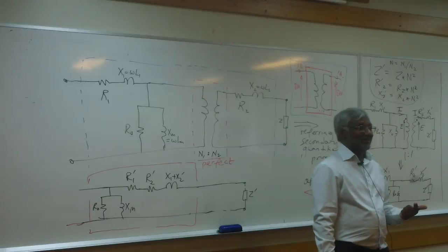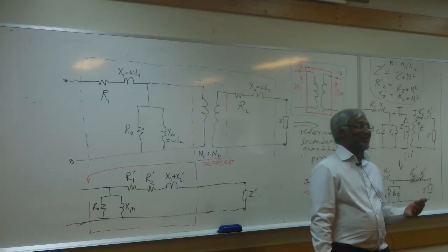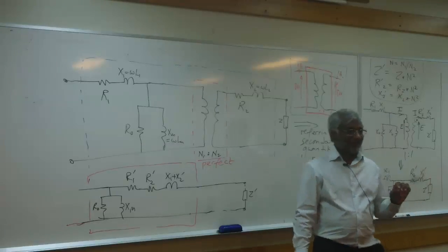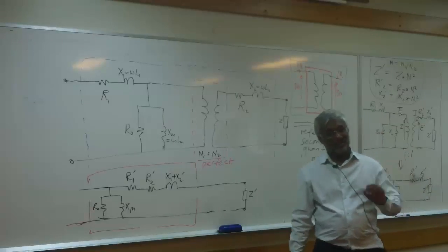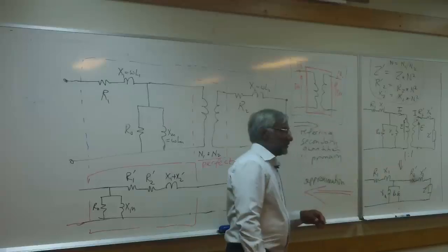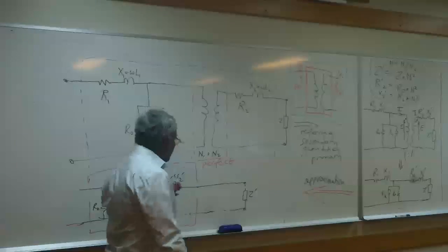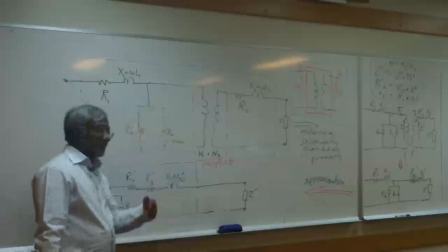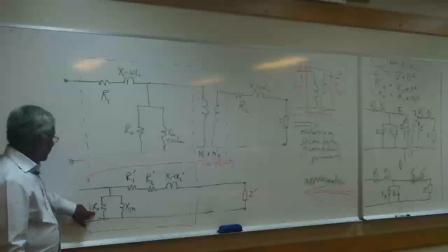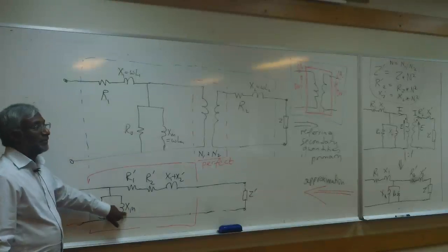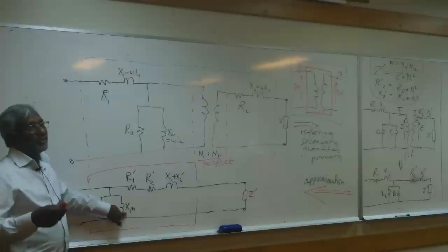Back-to-back tests, which I love. They don't do it in practice very often, but it's a very clever test. If you want to know why it's clever, just let me know. I'll tell you. It's very clever. Anyway, short circuit test, open circuit test. Most people are aware of that. Open circuit test would allow you to measure R0 and XM. In this course, we don't worry too much about that.